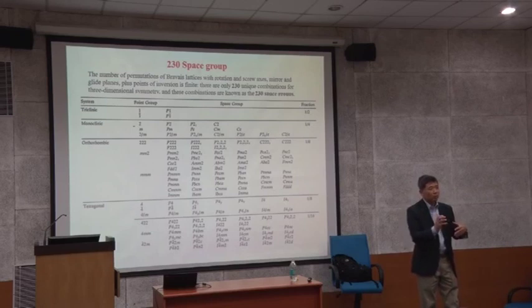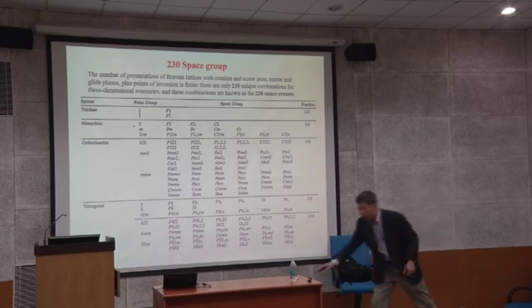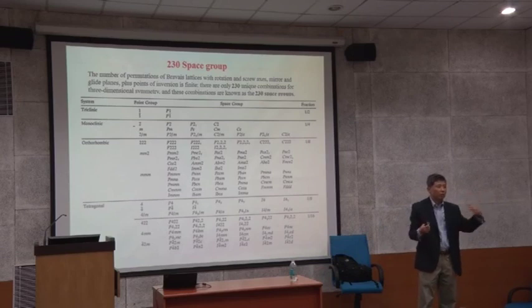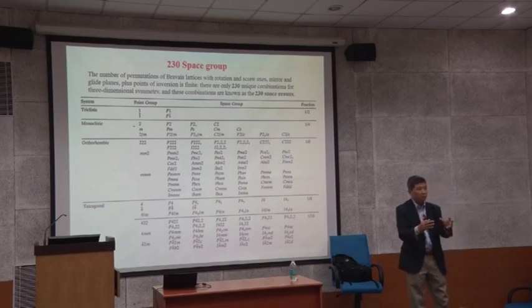But for the geometry of the sample, you have only one geometry, one angular freedom, which is powder diffraction, but you have 3 more degrees of freedom that give X-ray diffraction. Okay? So for X-ray diffraction, as I said, you have an incident X-ray beam with 3 different types of X-ray source I mentioned, but the interaction that happens is between the incident X-ray and the lattice.